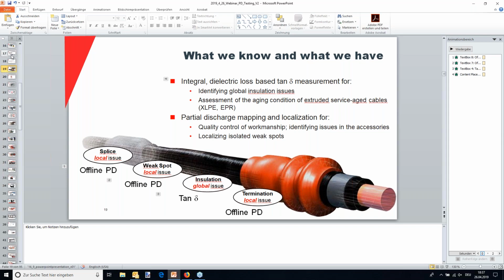The trending, when you say trending, meaning coming back every so often and watching what you're measuring, the absolute value there is also of importance, because if you go to a circuit today, you take the measurement, you save the data, and you come back 2 years from now, and the magnitudes have changed, that is one of the parameters that you judge the degradation by, because your magnitude went higher. So it's a combination of both. Look at the calibrated absolute magnitude to get a feeling what's going on, because magnitude is not the same as magnitude, as you could see in the case studies.